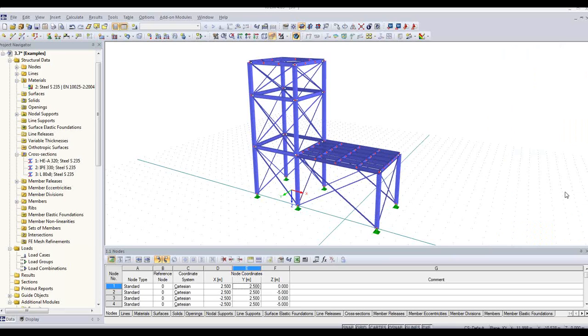Next, what we are going to do now is continue with creating some load cases and entering some loads, some point loads, some area loads, but there are many different load types, including temperature loads and imposed displacements and variable load types inside this program. We are using just a few basic tools today to demonstrate the general procedure of how to design such a steel structure. And I give the control back to Chelsea, where she can then continue with this presentation. Chelsea?